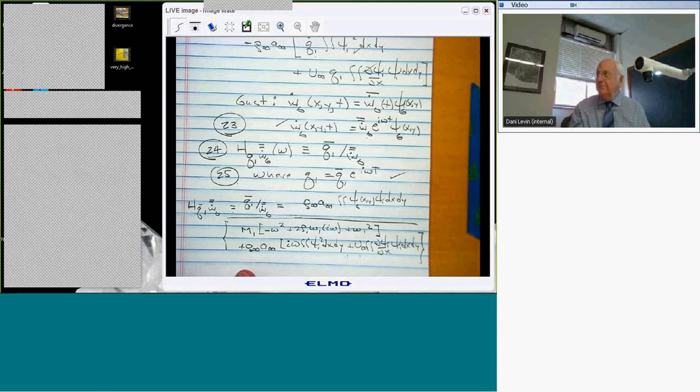Yeah. Okay, so I think this is right, but you can sit down in the quiet of your office and make sure I did the algebra right. Okay, let's interpret this a little bit physically. First of all, this term is the structural damping. It's really mathematically just like that term. So this term from the aerodynamics gives me aerodynamic damping. This gives me structural damping.